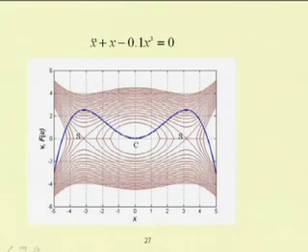But corresponding to the maximum, you just take this point and this point. Corresponding to this maximum potential energy, you can see the system will have a saddle node point. This point is known as the center point, and these 2 points correspond to the maximum potential energy, where the system will not move, or the system will have an unstable response. That is known as saddle node points. So, these 2 points are saddle node points and this point is the center point. In this case we have found 3 equilibrium positions. From these 3 equilibrium positions, one position is stable and the other 2 positions are unstable.